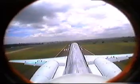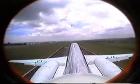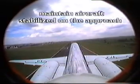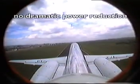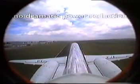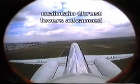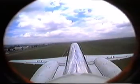The recommendations to cope with the delay in acceleration are very important. With a little bit of anticipation, it is quite possible to maintain the aircraft stabilized on the approach so that neither a drastic increase nor a dramatic power reduction is necessary. During approach, thrust levers should stay conveniently advanced to allow engine acceleration in case it is necessary to gain airspeed.